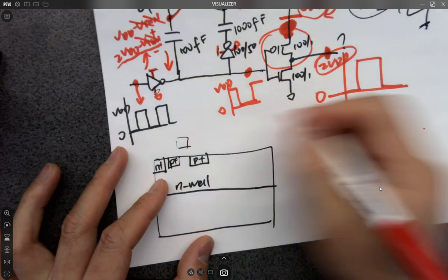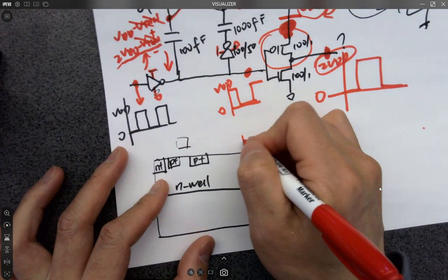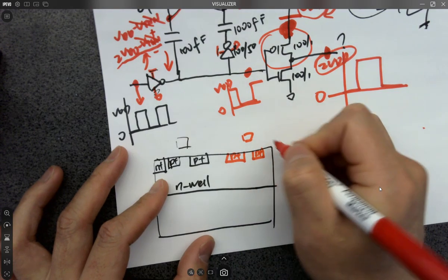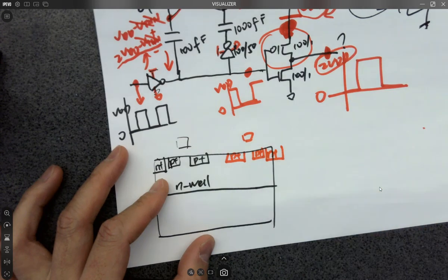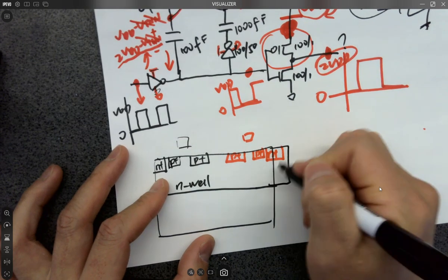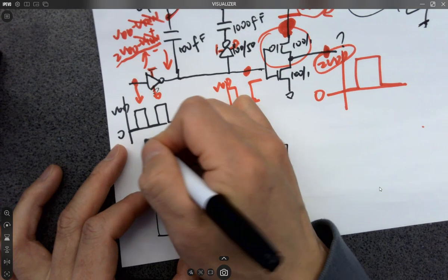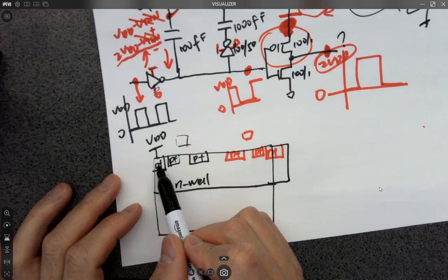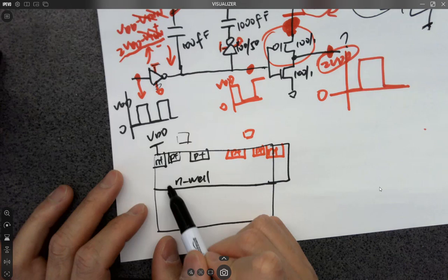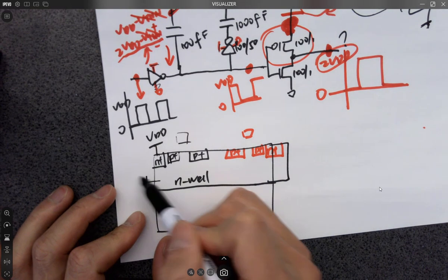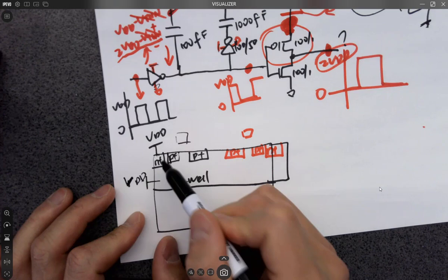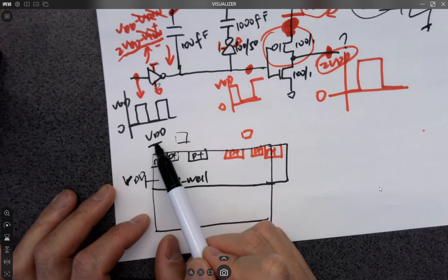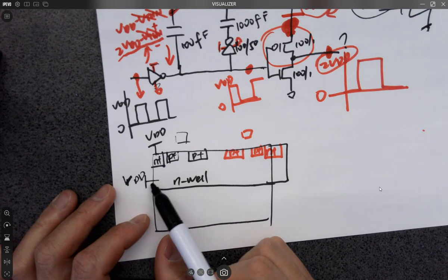Okay, look at this one. Here's a little imposter here. Every PMOS has a little N plus. Let's just draw N plus over here. Sorry about that. And all these are shorted to VDD. Okay, so if this N plus of the regular PMOSes are shorted to VDD, which means this N well is shorted to VDD. You agree with that? Because N plus is shorted to N well. These are same materials, they are shorted. So if N plus is shorted to VDD, your N well is shorted to VDD.